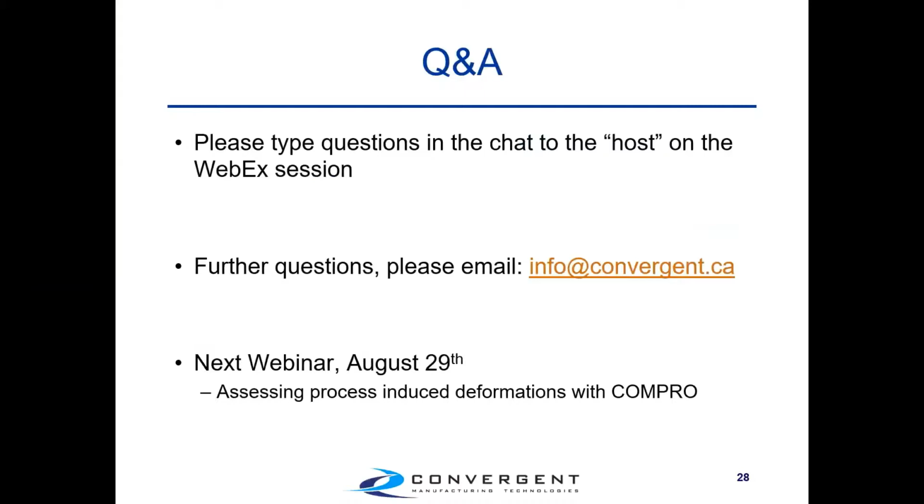Okay. Another question here, instead of honeycomb core, can we use foam core? Absolutely. Now, we don't have any foam cores in our open database within Raven right now, but since most foams are non-curing materials, you can typically get the properties off of a data sheet, and you can create a material file for that.